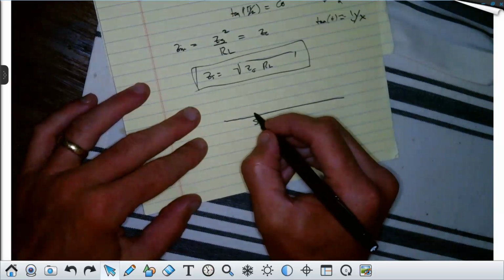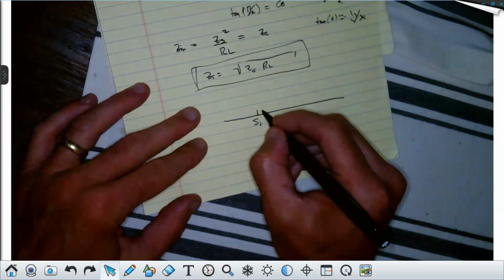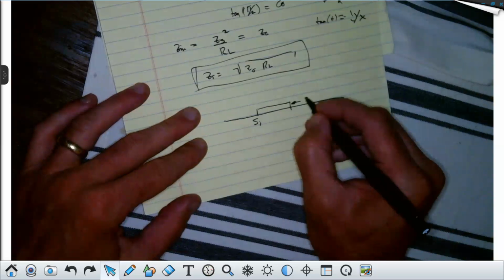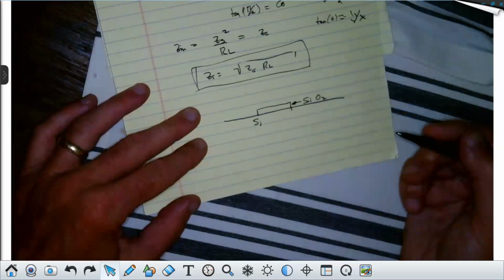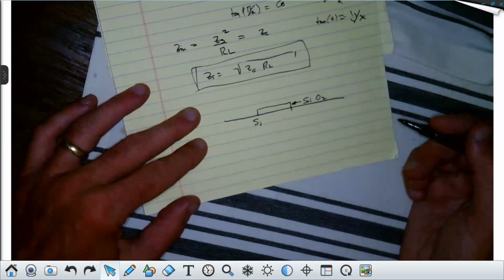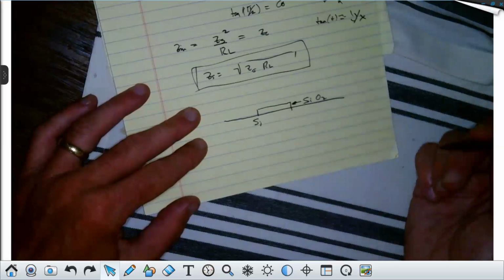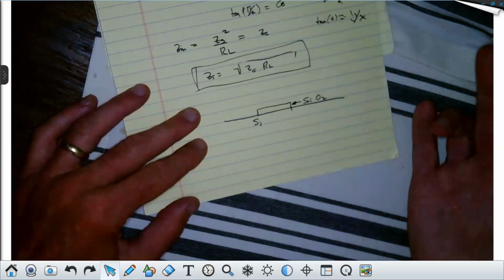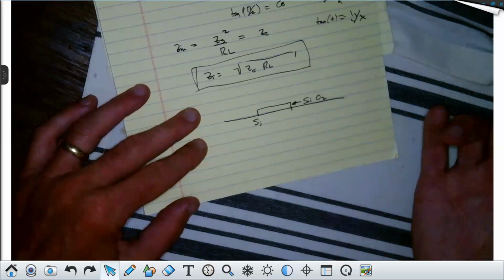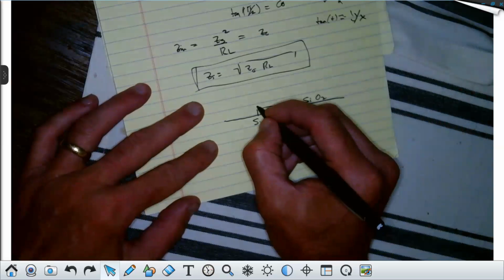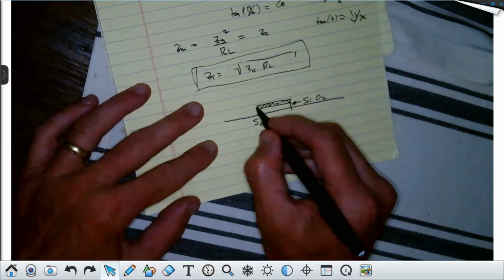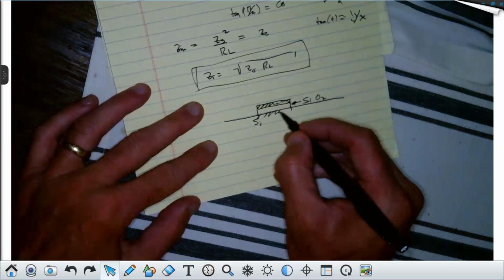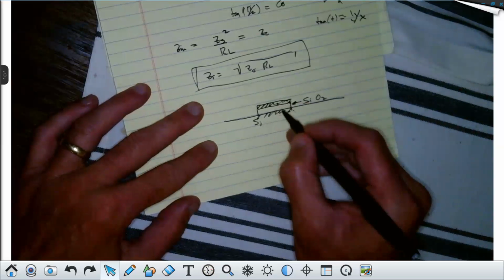And then you delineate a pattern. I'm not going to spend a lot of time on this, but you're going to have some silicon dioxide right here. This is not important. This has to do with masking and photolithography that you're going to get in another class. Have you had your microelectronics lab yet? If you've had this, you know about masking, you know about the acid wash, where you delineate a pattern. And then on top of this, there's going to be metal right here. Between this metal and this silicon is a transmission line.